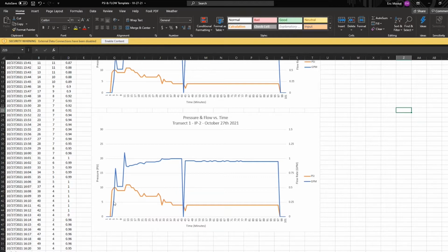The valve opened, flow came up, and it spiked up. So the unit started to restrict flow rate a little bit, and then it opened it back up again. We exceeded 1 GPM, which is our target, so it restricted again, and then it allowed the valve to kind of open slowly, and we established a fairly steady state for the rest of the injection with this little bit of a down spike here. This reflects where we switched over to a new batch tank.